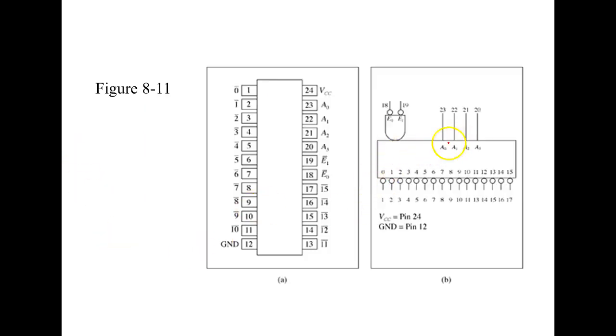The 74154 has 4 input pins, 16 output pins, and it's got 2 low active enables. So to make this guy here work, we got to bring enable 1 and enable 2 both low. And my guess, it's got a low active output, so whatever binary number we put on the input, that output should go low depending on whether the chip's enabled.